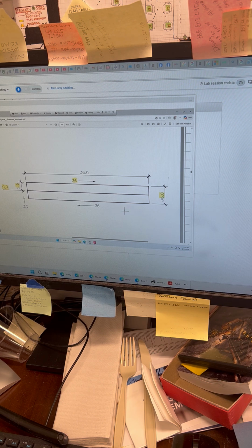Then another line down from here that is 5 units in the 270-degree direction, but we're not even going to have to enter those angles. We're just going to use our ortho and direct distance entry. Finally, back the other way, just like my rectangle, instead of 5 units and 3 units, this is 36 units and 5 units. Then back up 2.5 units, and finally we'll add one more line right down the middle to represent the pane of glass.